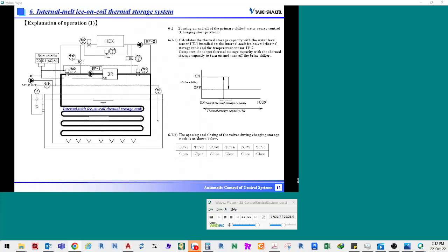It is formed by the brine chiller and tube pipe and the ice thermal storage. The load generated in the room includes people load, lighting, the brine water and equipment heat separated from the circuit. Those loads are factors in heat gain. If the chilled water pump is considered, only cooling load can be sent to cooling. People load includes sensible heat load caused by heat generated by people and latent heat load, obtained from comparison of the thermal storage capacity of the ice thermal storage tank and the target operation and room temperature.